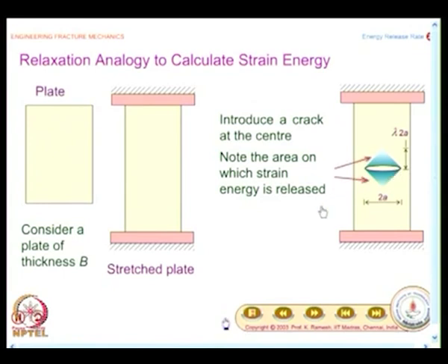See, in fact, even in your design courses, when you develop how to understand the concept of shear, suppose you take a shaft and put a keyway and put a key there, which is subjected to torsion, and you want to visualize that shearing action takes place on the key. If you are given a strong metallic key, it is difficult for you to visualize. One of the tricks that is employed there is, imagine the key is made of frozen butter, then you can visualize when the shaft is twisted, you will find that shearing action takes place. You are able to feel it with the component in question.